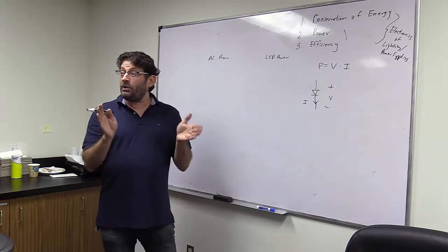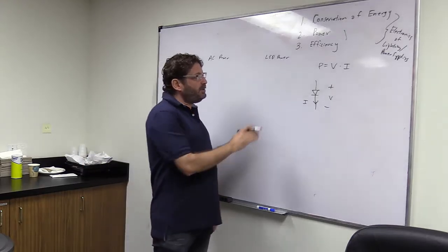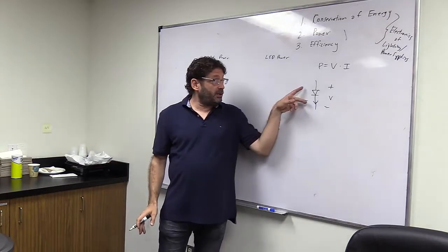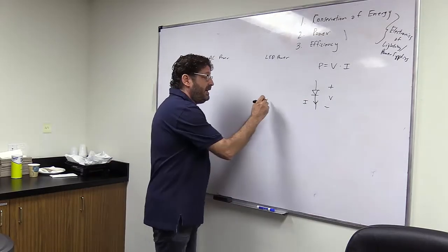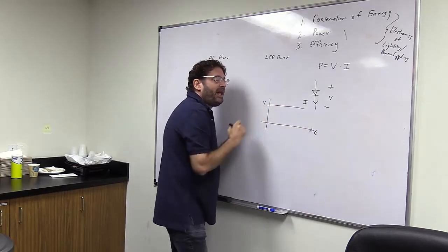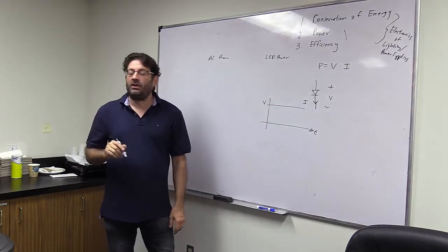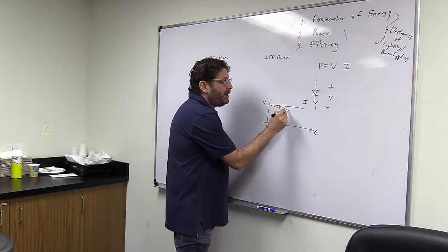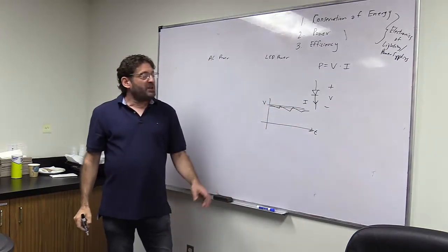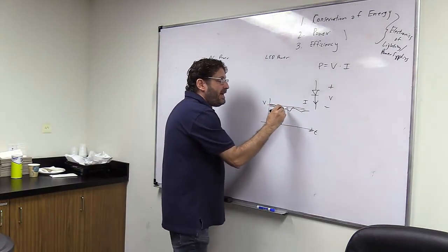Good news is that most times in LEDs, the signal that you see across here is flat. There's no change in time, right? The volts will be like that. That's not always the case. You might see some ripple from a power supply on here like this, but that's close enough to an average, right? You might see PWM, and that would be a problem.